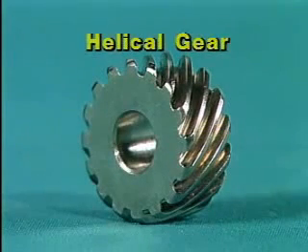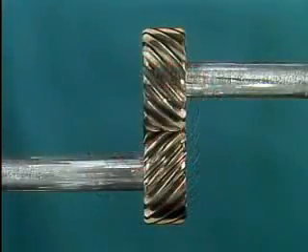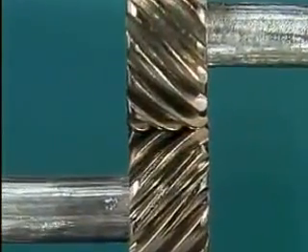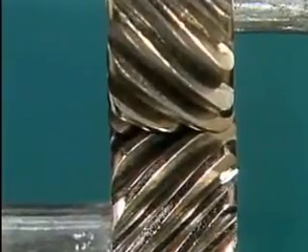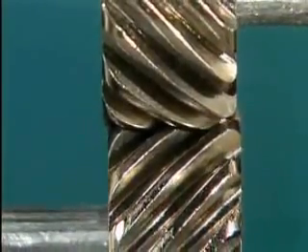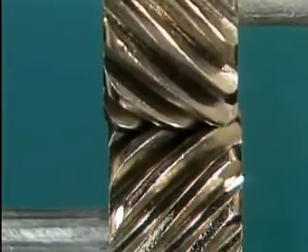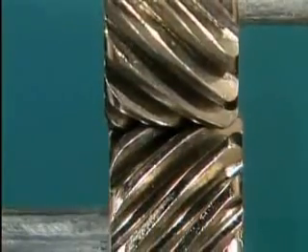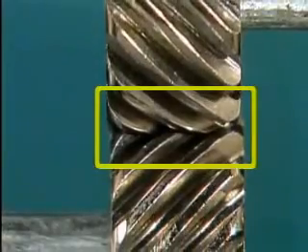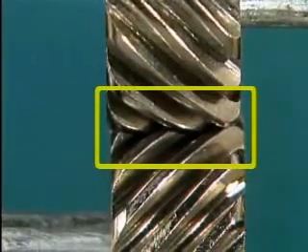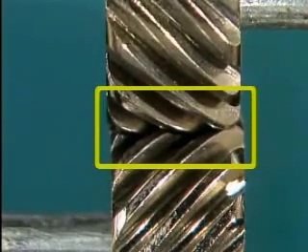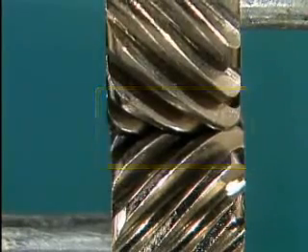As two helical gears mesh, the contact between the two gears begins at one end of a tooth and extends gradually across the width of the tooth. This allows the gears to run quieter and smoother. This is also true for the spiral bevel gear. If the face of a helical gear is wide enough, several teeth will be engaged at the same time. This multiple engagement of gear teeth allows a helical gear to carry a larger load across a single gear set.